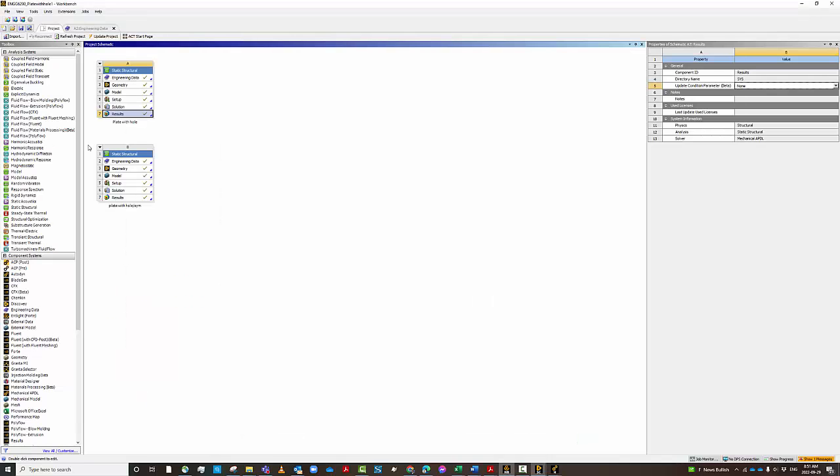Okay. So again, you can create more than one project. So basically, you can select different kinds of materials. For geometry, you can use different types of ways to generate geometries. And then in the model, you apply your loads and your boundary conditions. In the solution, you see the solution and the results.